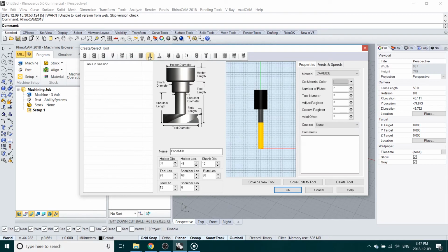The face mill is a tool that has a wider tip on the bottom portion. This can increase the amount of material being removed in a single axis cut and can remove a larger amount of material from the surface of the stock. The dovetail mill can be utilized to create a tapered condition in the stock that would not be possible using conventional bits in a 3-axis machine. However, this is limited to the taper angle and the flute length of the bit.